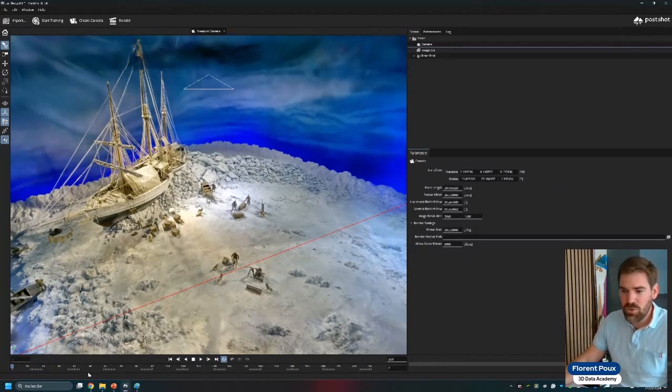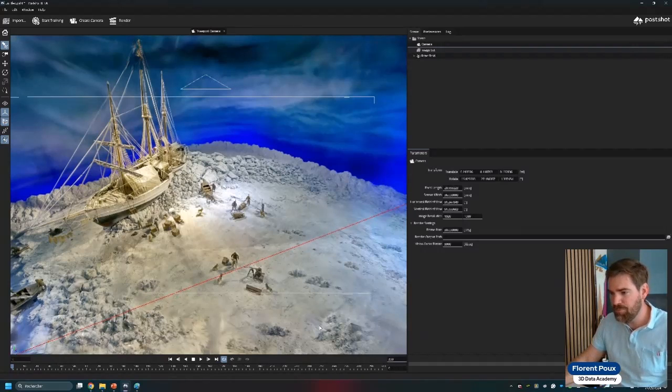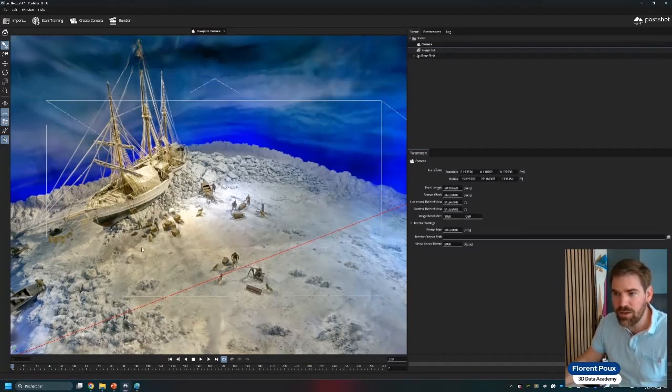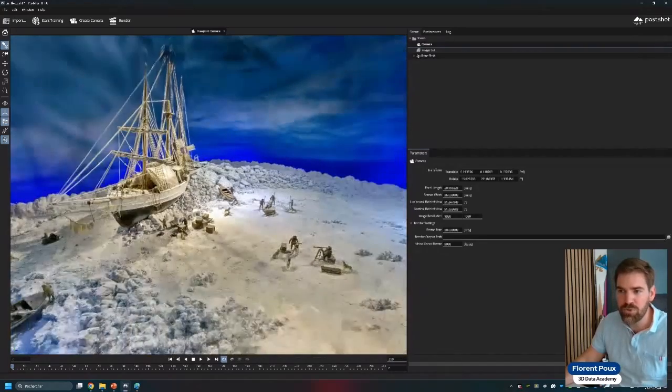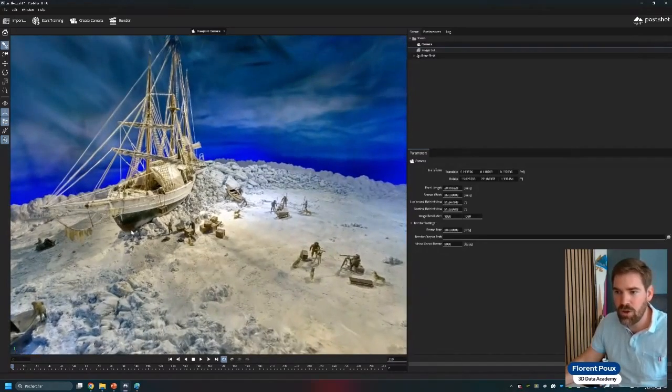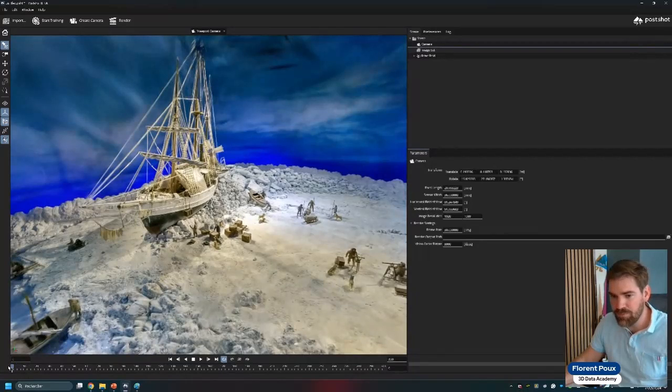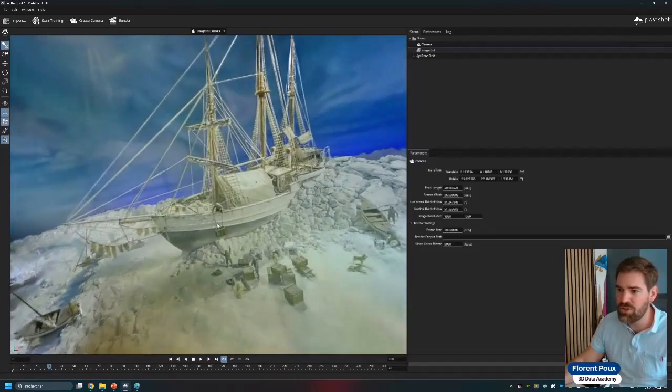And then you see you have a line here, which is basically each unit, 1, 2, 3, 4, 5, is a frame. And whenever I export, I will say how many frames per second I want to have. So if I have 30 frames per second, I want 10 seconds, I will say 300 maximum. And now I would say this could be my first position, for example. You will see how I do. And I create a key. And then I go at 1 second, so 30 frames. I will move to another position.